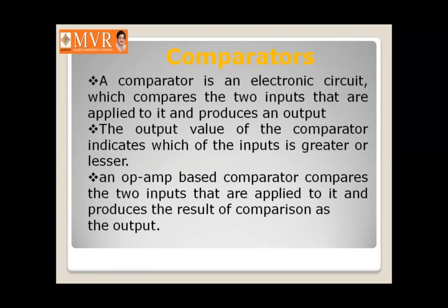First of all, we are going to discuss about the comparator. What is a comparator? The comparator is a circuit which compares two inputs, where one of the inputs is a fixed value and another input is a time variable signal. That fixed value signal we are calling the reference voltage.